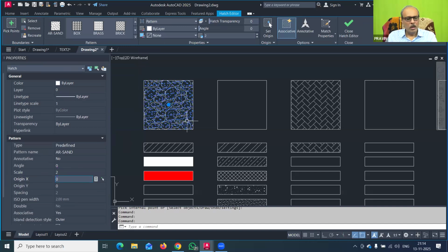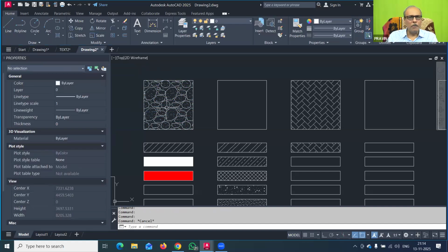So in this way, you have to use two patterns simultaneously, the boulder and murum filling with the sand filling also. So it is showing the earth and the boulder stones. So in the plinth, whenever you want to fill such a type of filling, there are two patterns simultaneously, sand and boulder, that you have to use from here. So this is the thing you require to be given in the cross-sectional drawing. When you draw the load-bearing structure drawing, building drawing, there you require this one.